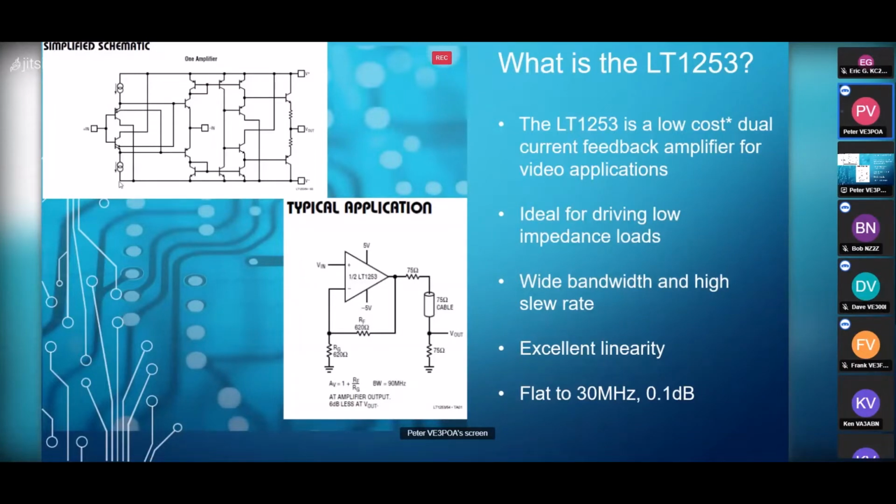It's ideal for driving low impedance loads, which is great because we're working with 50 ohms and wideband and high slew rates. Excellent linearity, and they claim flat to 30 megahertz, 0.1 dB. I didn't quite get that good, but not bad. Of course, my setup is nowhere near like theirs, I'm sure.